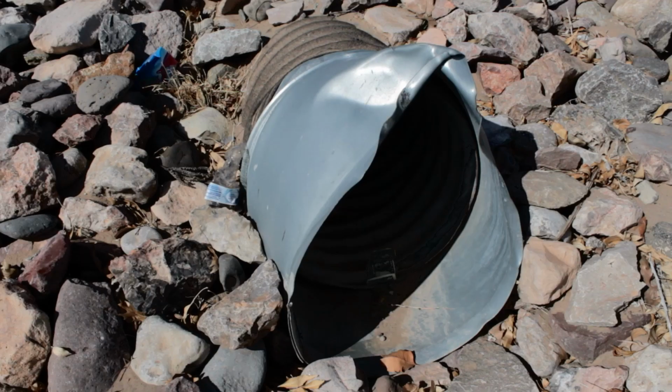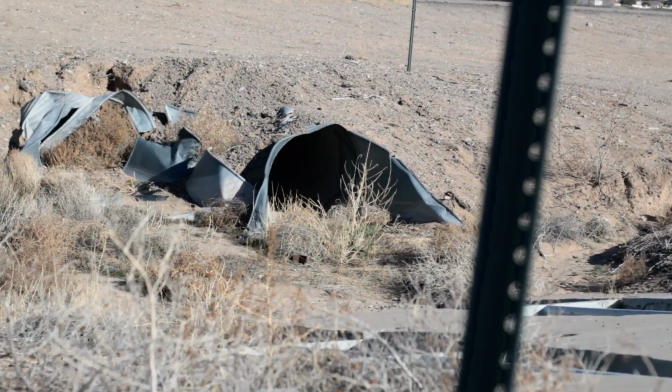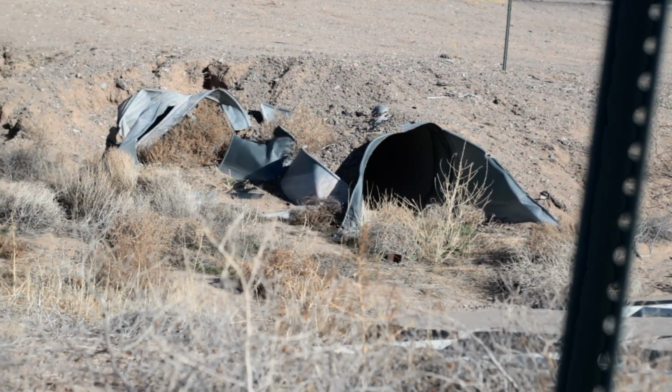These are categorized as the damage and corrosion of the culvert, and the level of it will depend on your judgment as inspector. Let's talk about physical damage first. For metal culverts, we can find minor, moderate, and heavy damage. I'll give you a hint. If the pipe opening is significantly deformed, it can be moderate or heavy damage.